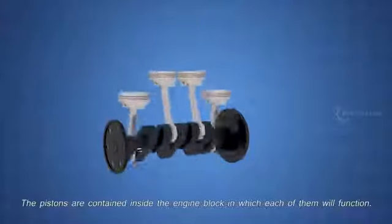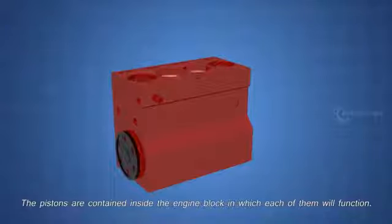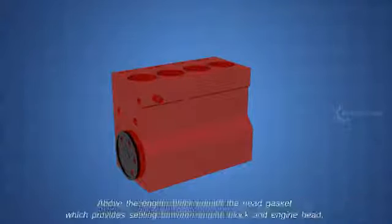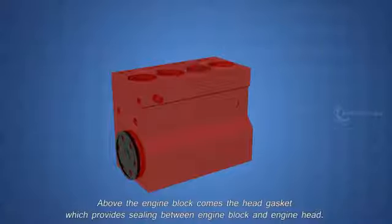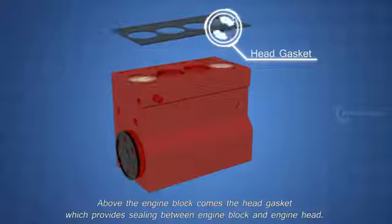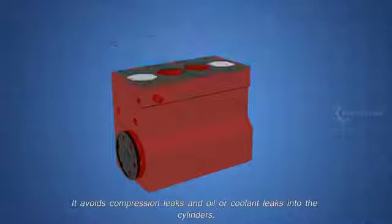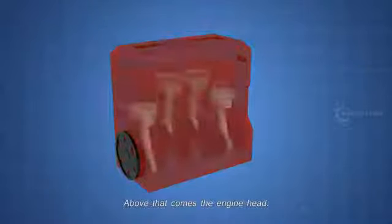Now, let's see how these parts work together. The pistons are contained inside the engine block, in which each of them will function. Above the engine block comes the head gasket, which provides sealing between engine block and engine head. It avoids compression leaks and oil or coolant leaks into the cylinders. Above that comes the engine head.